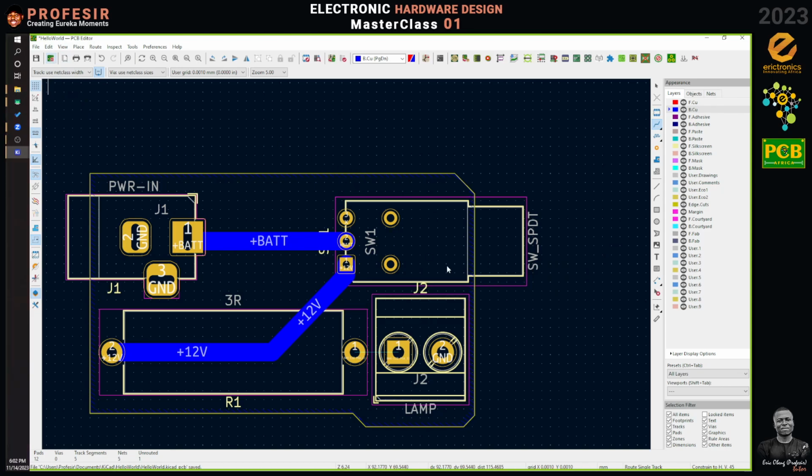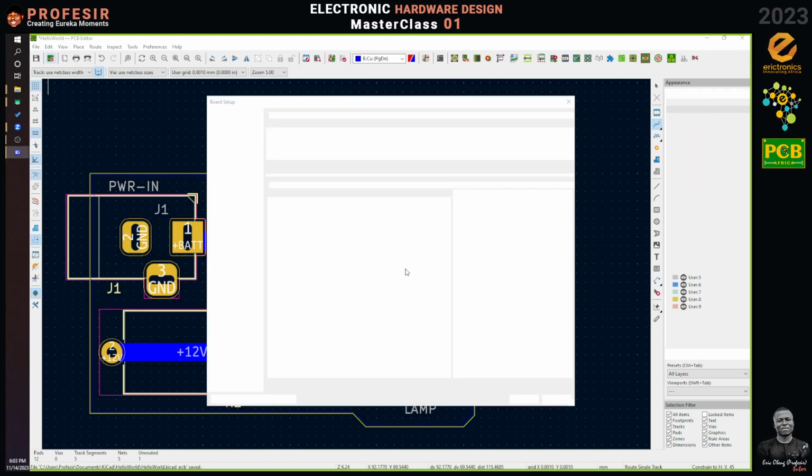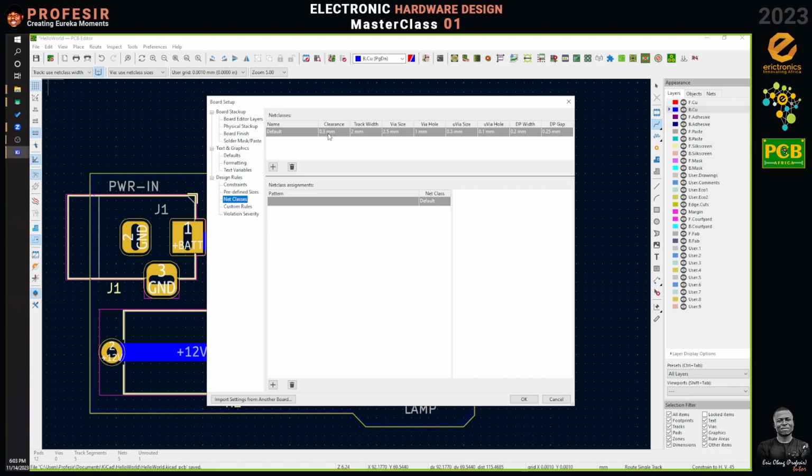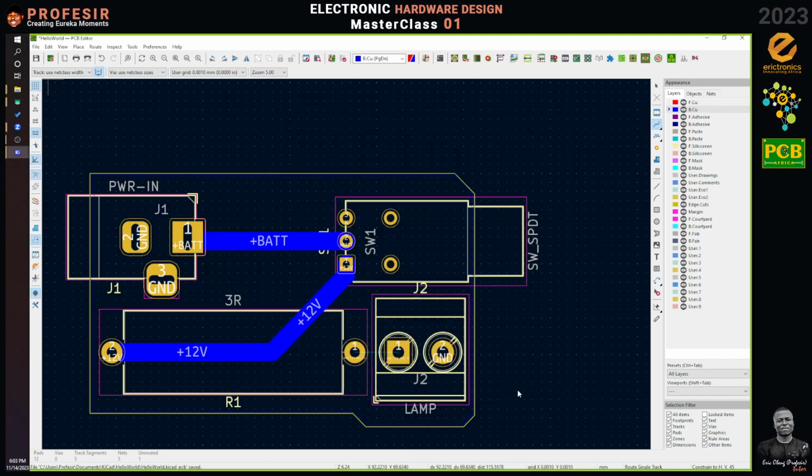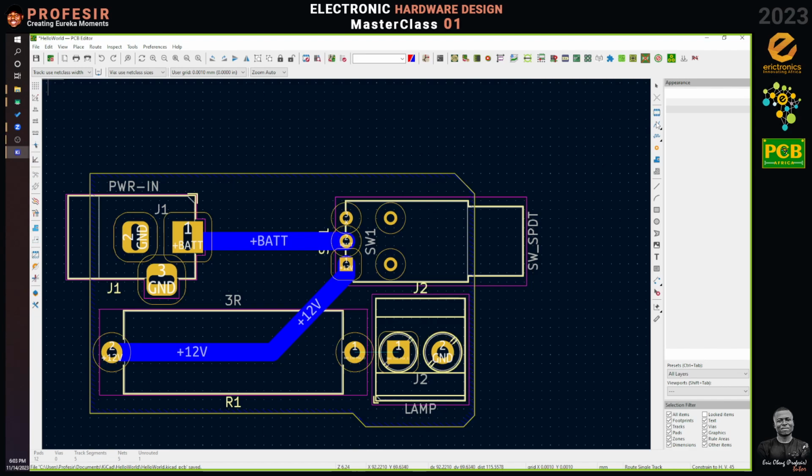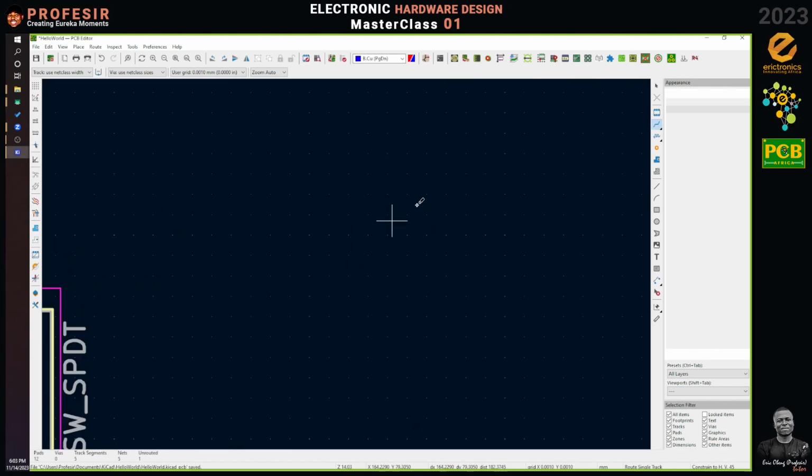Why does this thing take time to launch? Okay, so you see how simple all these things are. I know if this is your first time, it may not be as simple as I'm describing it, but basically it's simple and nice. So we come back here and change this from 0.3 to 1. Definitely KiCAD is going to complain, but we intentionally did that, so we don't care. So now we are left with just one more trace to route.